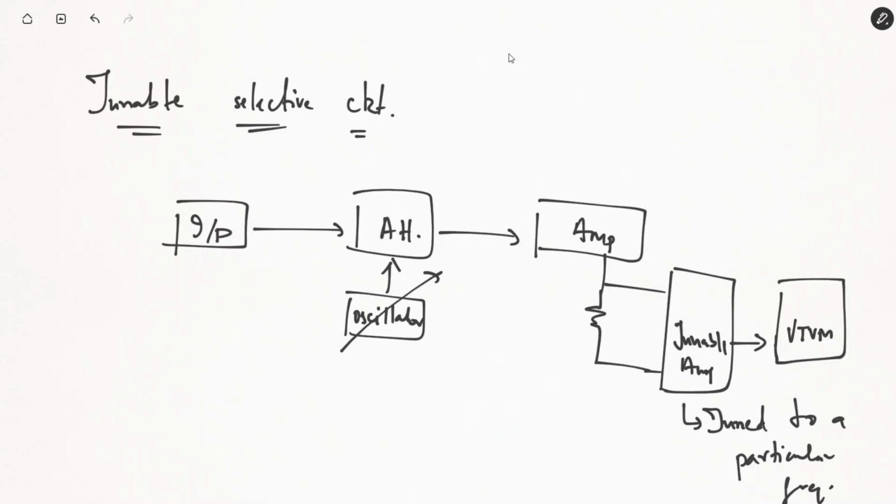We already know that all of the frequency components are a fraction of the fundamental frequency component. So by tuning the attenuator to allow 100% of the fundamental frequency component, all the harmonic orders will be passed on as a ratio of the fundamental frequency component.